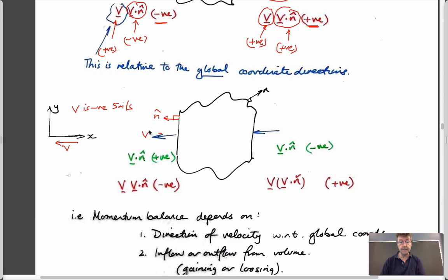This is the velocity here, and so this term has to be positive, because it's going out of the system. Our convention is out. But the direction of this is in the negative x direction, so this is negative, and a negative times a positive is a negative. So if you take the scalar value of whatever the velocities are and square it, you'd have to apply a minus sign to that to get the right component.